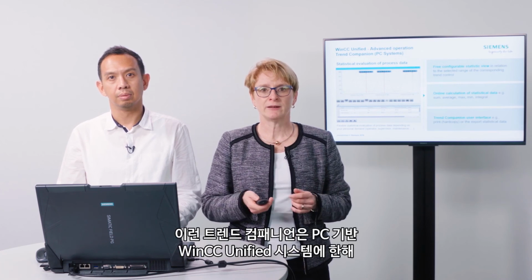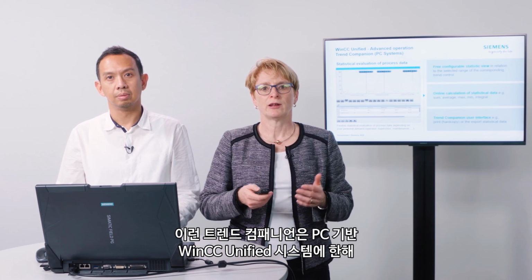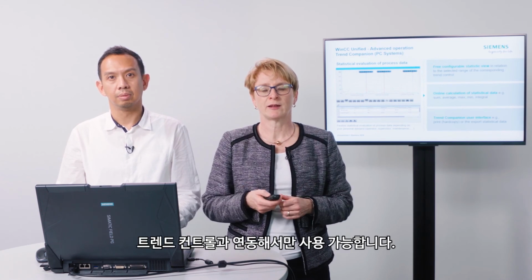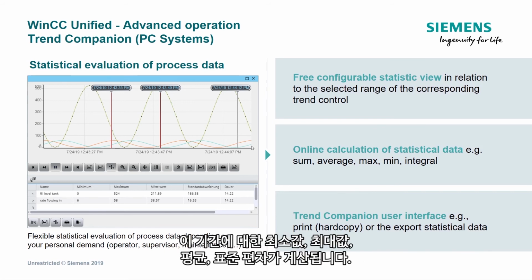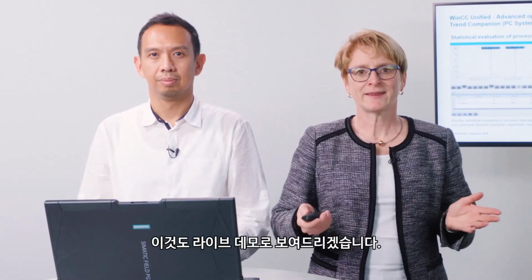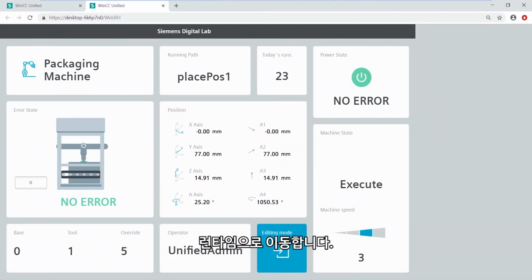The Trend Companion can only be used for PC-based WinCC Unified systems and in conjunction with a trend control. Online statistical calculations are carried out for a time period selected in the trend control. The minimum, maximum, average, and standard deviation for this time can be determined in this way. We'll show you this again in the live demo as well. Let's go right to the runtime for this.